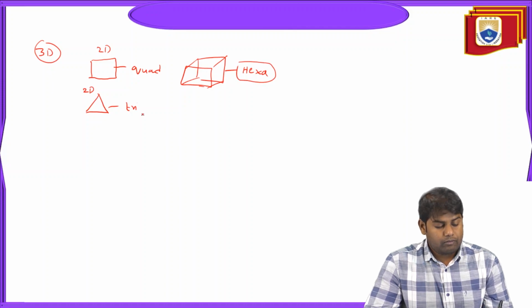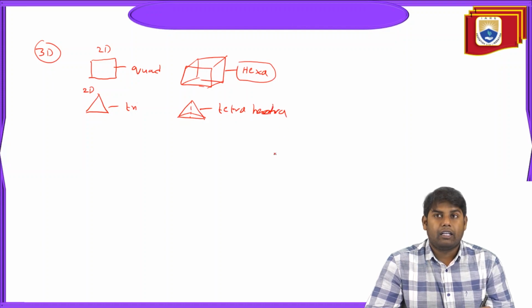Okay, so now when we take this one, in terms of prism actually, this is called tetrahedra. This is hexahedra. This is tetrahedra. So here you can see that the three-dimensional entity for the structured mesh is a regular entity. So we call it hexahedra, and for the unstructured mesh, we call it the tetrahedra. Fine.